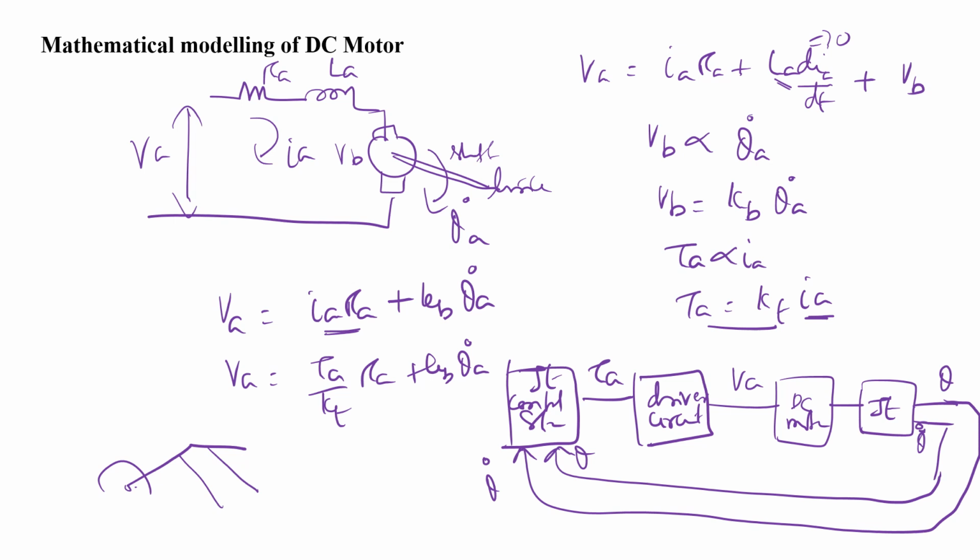Okay, so here you have this joint control system. For example, let's take this as joint 2. So we have one block, the joint 2 control system. To that joint 2 control system, this theta and theta A dot are given. How? See, here you have the gear, here the motor, and here the sensor. This sensor will give you this information. The sensor information, which is angular velocity and angular position, is given to the joint control system. Then the joint control system has the set point, which is already implemented in it. It calculates using theta and theta A dot, the velocity, and then it will give you the torque.